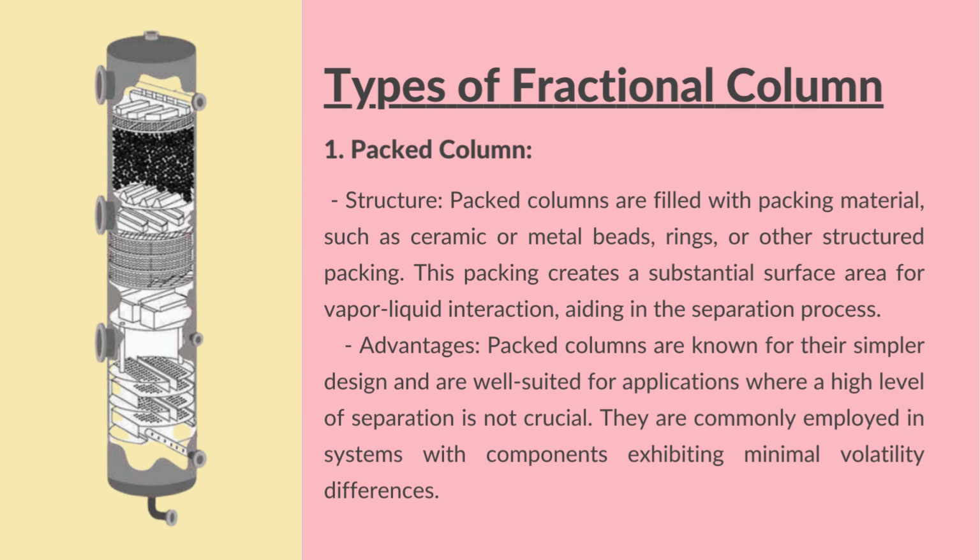To summarize this, the packed column is filled with packing material made up of ceramics, metal beads, rings, or structured packing. The objective of packing is to provide surface area for vapor liquid interactions. And the main advantage of the packed column is that it is suitable for certain applications and it is simpler in design. Okay guys, so this was a type of fractional distillation column.